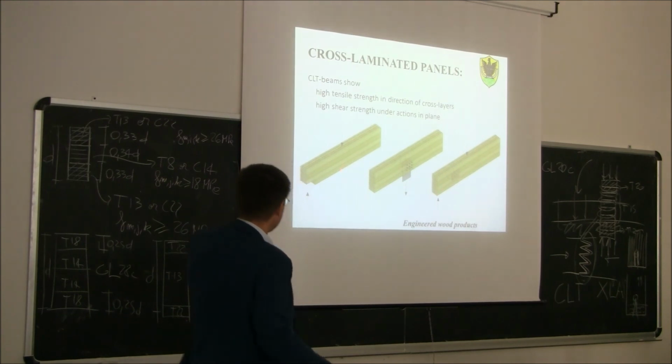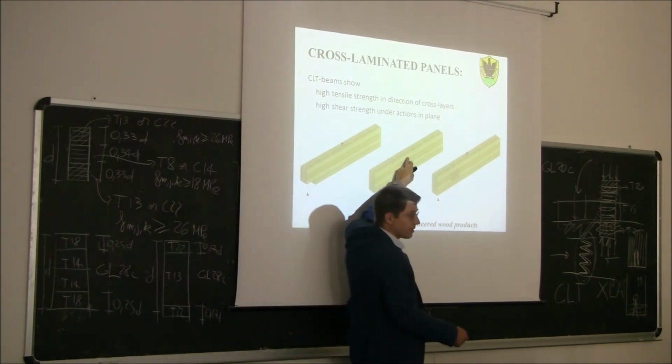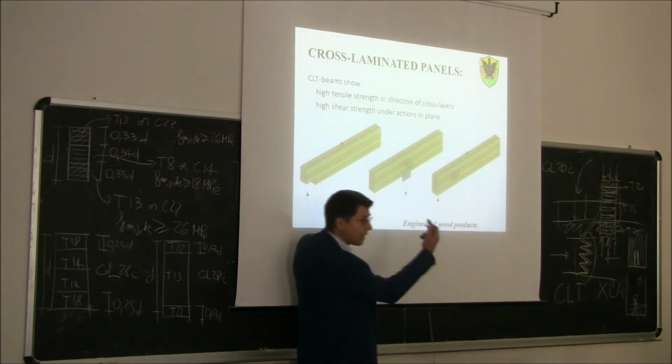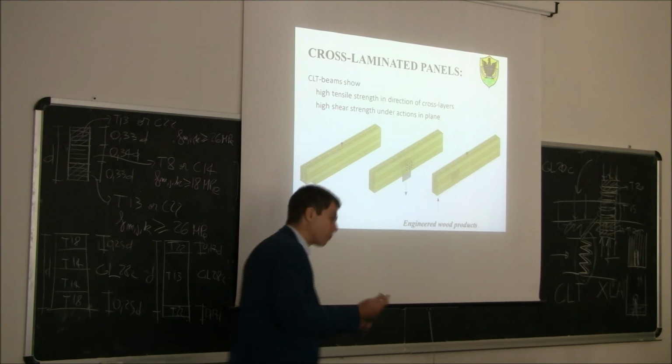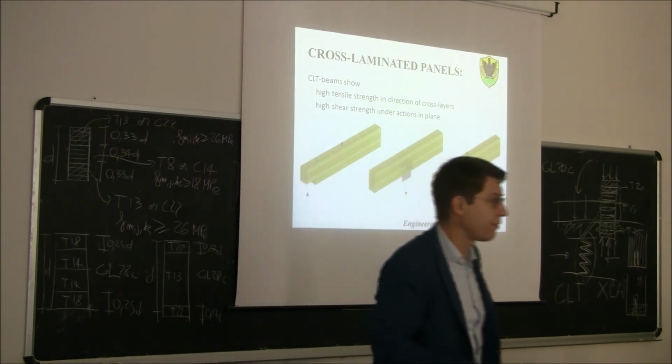If you use cross-laminated timber, you don't have this problem anymore. Why? Because the secondary stresses this time are taken by those 1, 2, or 3 layers parallel to the grain. So parallel to the secondary stresses. More or less what we were discussing before.